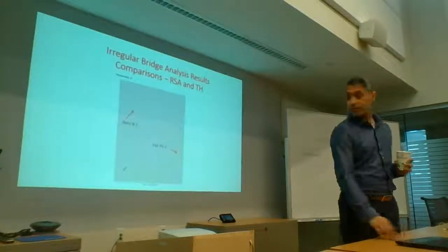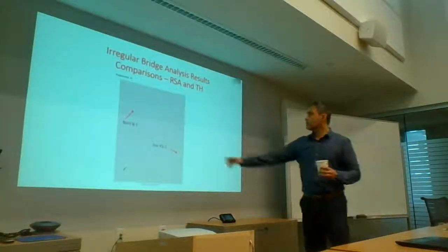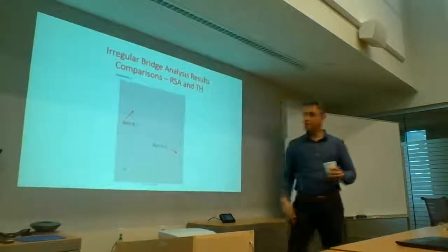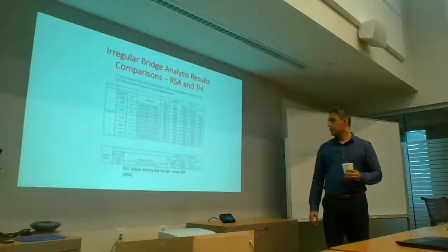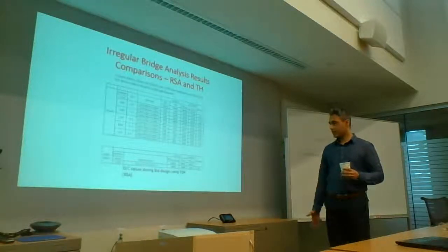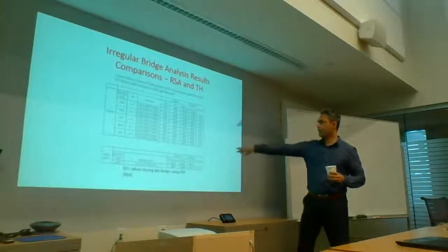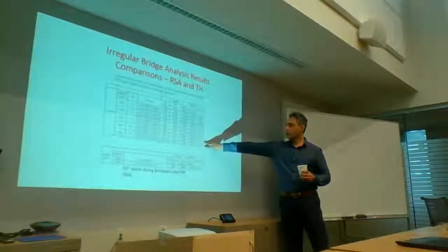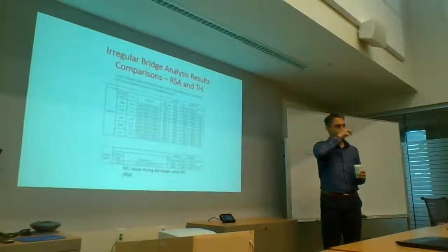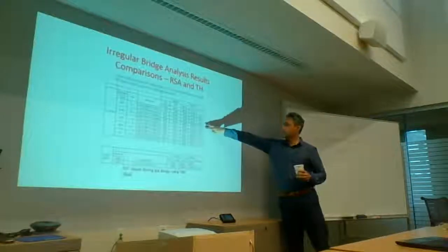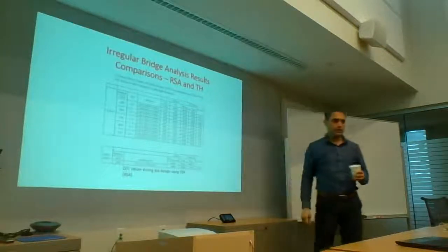This is an irregular bridge again, a highly curved ramp on the Evergreen Line. This was a straddle bent and then single column bents offset from each other. We did some preliminary work on it during bid design, and we found our D/C ratio for the drilled shaft was 0.85, but pay attention to this. B11 is where we were overstressing it by a little bit, so 10% to 30% overstress. And everything else, P13 is getting a bit close, but the other ones are not that close.